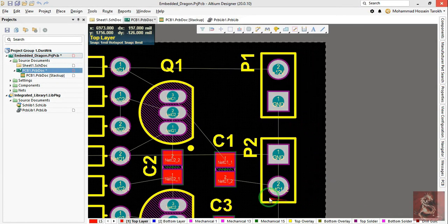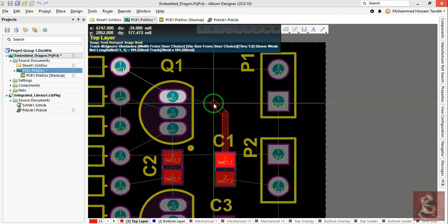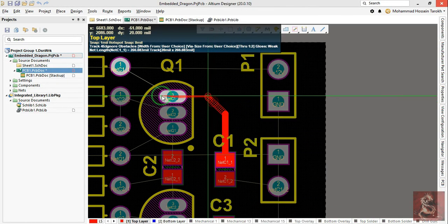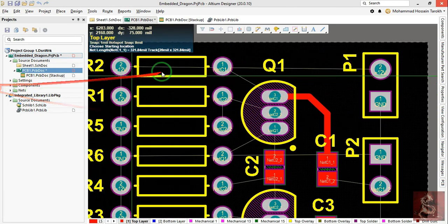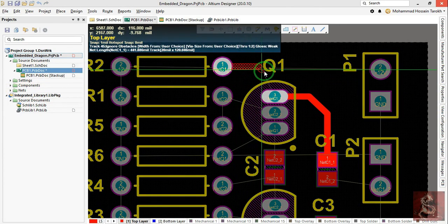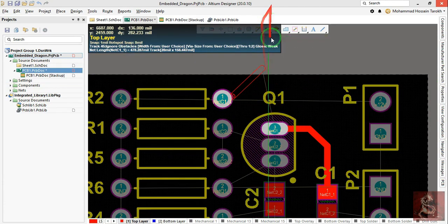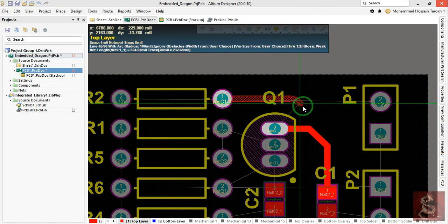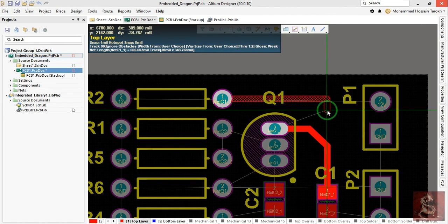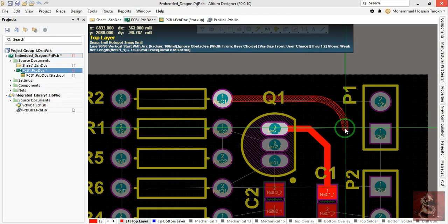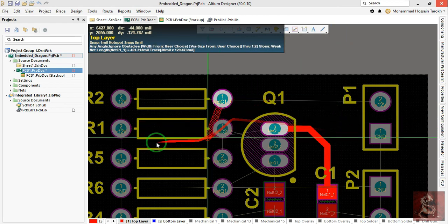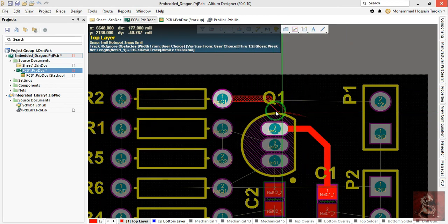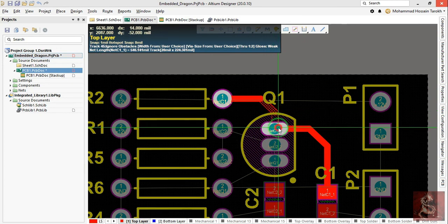Now when I want to try to route it, it allows me to have a bigger one, and this is fine for this case. As you see, I move them. You can also change the direction of your movement by space, and if you press shift space you can also change the corners. You can make it 90 degrees, you can make it like this, or as you want, but the best is usually 45 degrees.